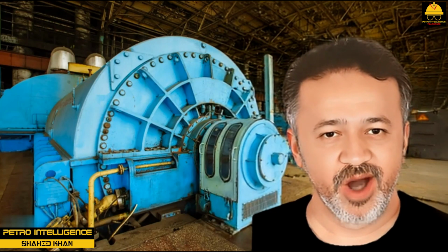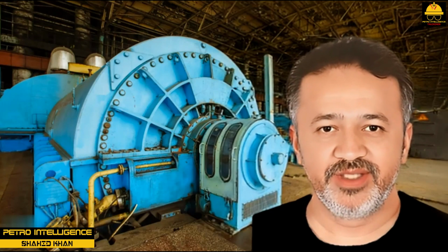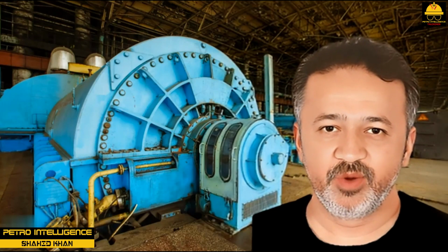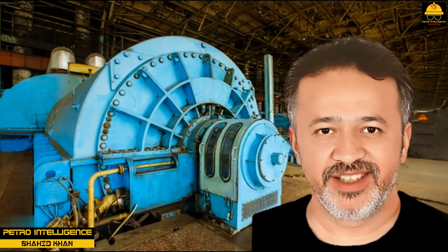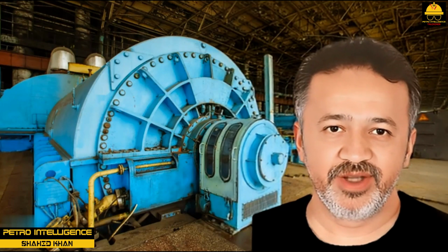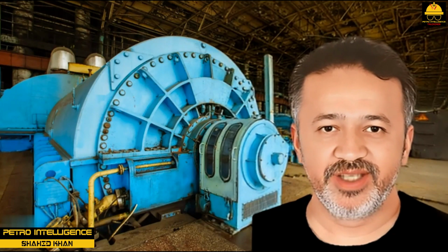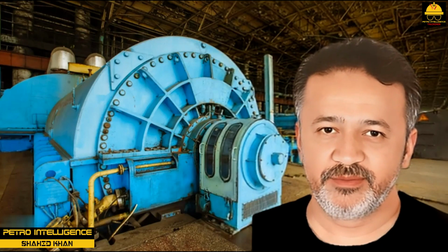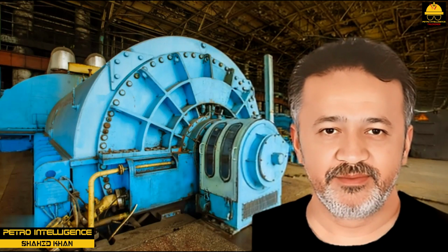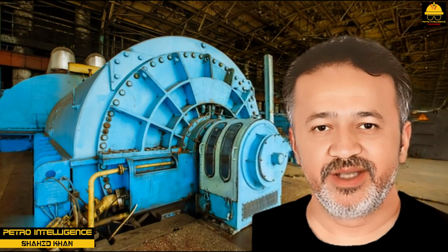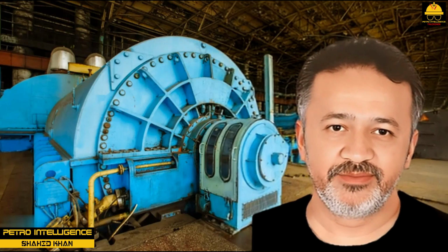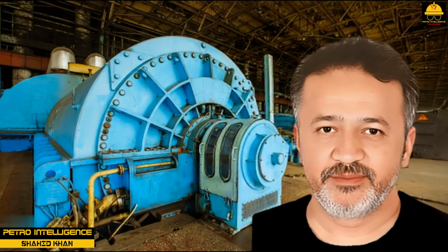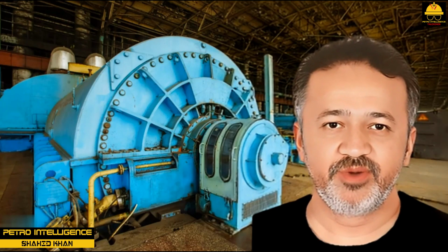Inlet steam pressure problems can also cause a steam turbine to hunt. The chemical processing industry attempts to maintain constant pressures on utility steam headers. Occasionally, boilers go down, or larger demands are made on the system. A fluctuation in the suction steam pressure affects the turbine. On hot days, the system may work perfectly, but cold weather might create problems for your turbine.